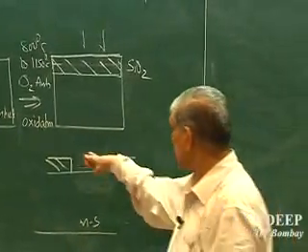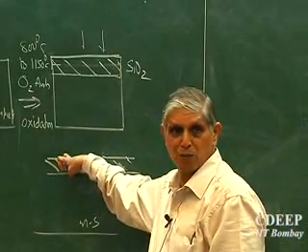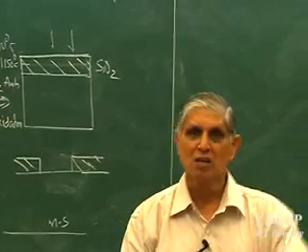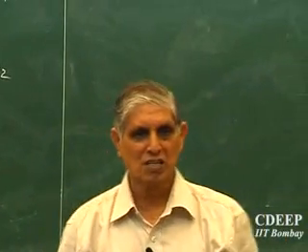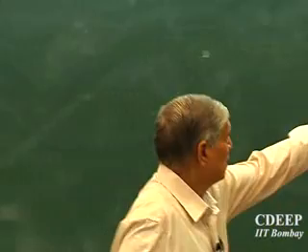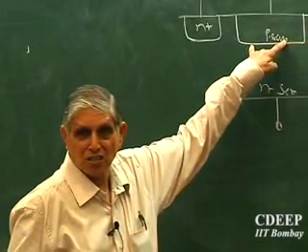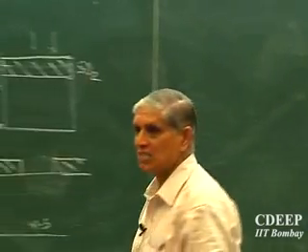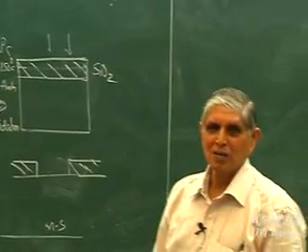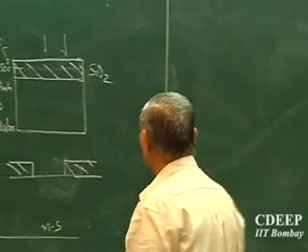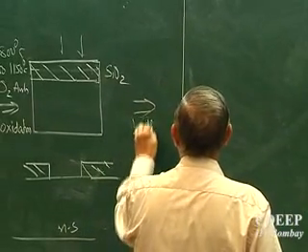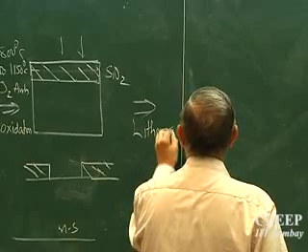Please remember, when I introduce P impurities, this area will block, this area will block, only the silicon which is now available to me, in that area impurities can go, and then in this area I can introduce impurities. Is that clear? So this is called masking. The word used is masking. So how do I do it? I use what we call lithography.